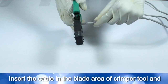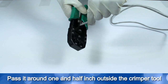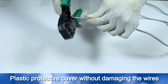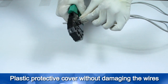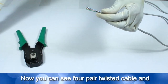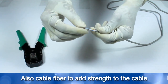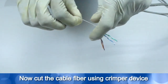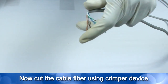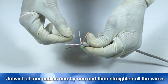Insert the cable in the blade area of the crimper device and pass it around 1.5 inch outside the crimper device. Now hold the cable and carefully cut the outer plastic protective cover without damaging the wires. Remove the cover carefully, and now you can see 4 pair twisted cable and also cable fiber to add strength to the cable. Now cut the cable fiber using the crimper device. Untwist all 4 pairs one by one and then straighten all the wires.